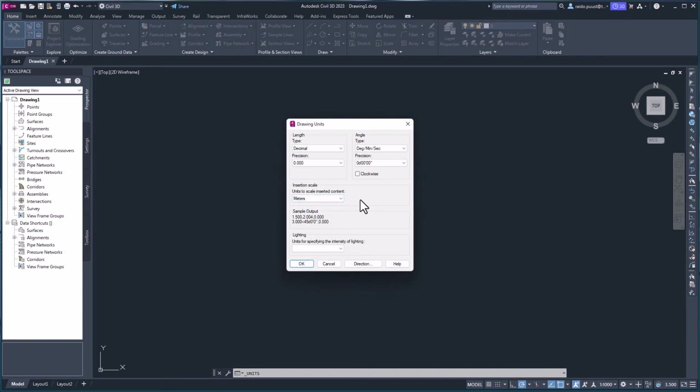That was defined in my selected template, and it's important that you select the right template, otherwise you probably mess up your drawing's content as well as tools that are available, because in Civil 3D, if you opened your product through metric version, also by default you see some default content in metric units. Those are different things, but it's important that both are from the same unit system.